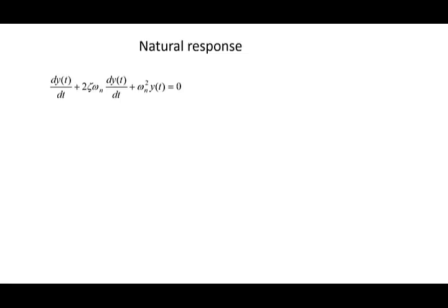In this lab, we want to use the natural response of a second-order mechanical system to identify model parameters, the damping ratio and the natural frequency for the system. We'll use those parameters to design a filter and then build an overall state variable model for the third-order system, and correlate that with our data.